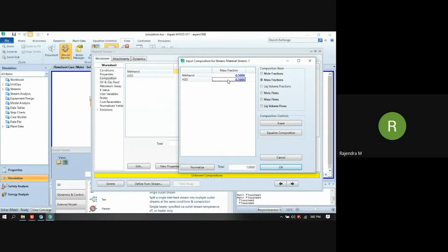In some cases, there is a Normalize tab over here. In some cases, you have a very large number of components. When you have a hydrocarbon gas mixture, there will be methane, ethane, propane, water, carbon dioxide, nitrogen, and so on. So many gases are there. The client sometimes provides limited data, like a range of the data, and some of the values they will ask you to assume based on the literature or your experience.